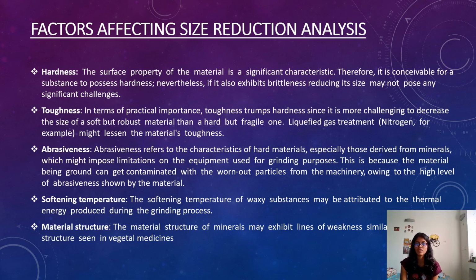Liquefied gas treatment, nitrogen for example, might lessen the material's toughness. Abrasiveness refers to the characteristics of hard materials, especially those derived from minerals, which might impose limitations on the equipment used for grinding purposes. This is because the material being ground can get contaminated with worn out particles from the machinery owing to the high level of abrasiveness shown by the material.